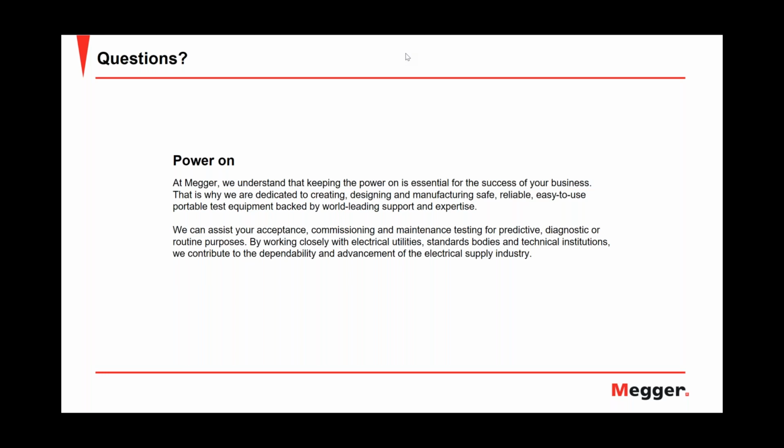So if you have a 16 kV thumper for this test, just put it to 16 and let it ramp up. Because you assume it's a faulted cable, which failed at operating voltage, it saw operating voltage, and then the insulation gave in. So you expect the breakdown to happen at a lower level. And typically on XLPE cables, like Javier explained, you expect the breakdown to be much lower, well below 12 kV. So just set it to a reasonable number. Don't overvoltage it to crazy values, just let it ramp up and wait for the breakdown. So you're not carrying out a DC proof test.